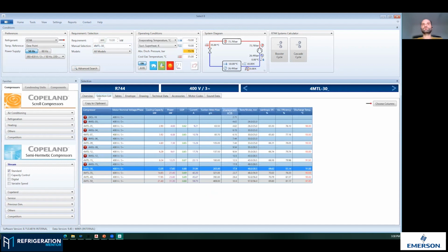And there is also not only the one compressor model, but there is the full family, and you can see which is, let's say, without any warning sign here. This is a compressor which perfectly works at the set condition, the chosen compressor, the chosen condition, and there are another ones from that family which have some, for example, exclamation mark, and if you go above it, you can see the warning. So this 4MSL compressor at this condition is above the maximum allowable condensing pressure, and it's simply because of the fact that it is LT compressor, it is subcritical compressor here.